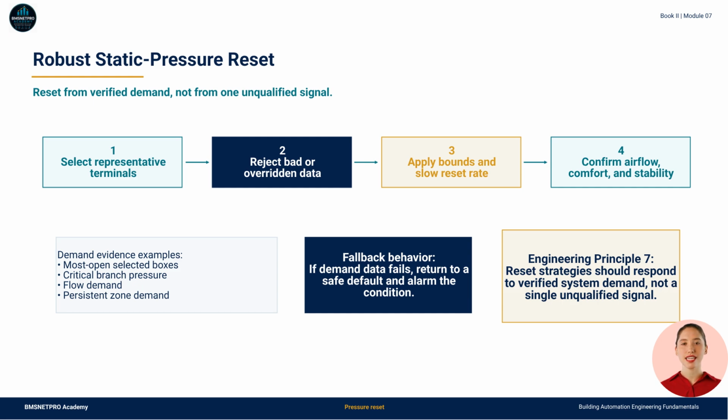The purpose of reset is not simply to lower pressure. The purpose is to supply enough pressure for verified demand while reducing fan energy and avoiding unnecessary reheat, comfort complaints, noise, and unstable operation.